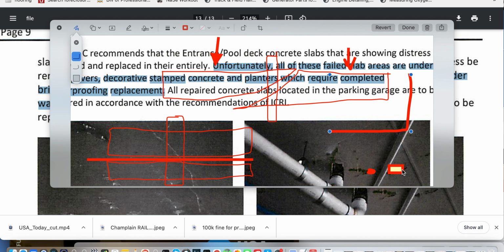And this one out to here is 19 feet 4 inches, 19.4 center line. So let's just round it a little bit. 19 minus 11. We're only talking 7-8 feet from here to here. And yet the sagging that took place created this core sample. So side profile, here is the drop slab detail.